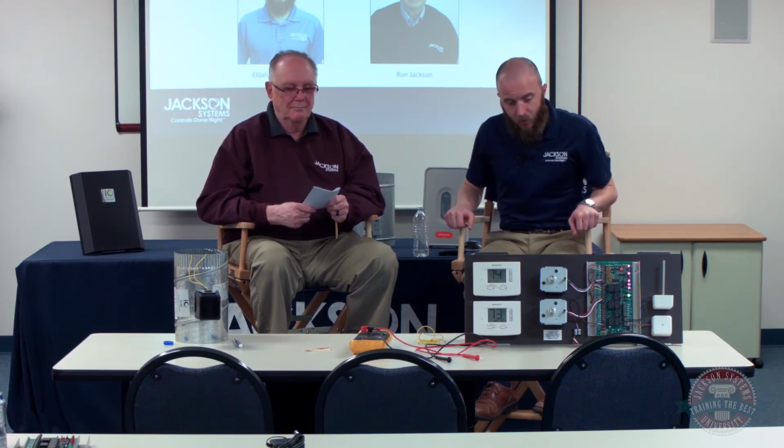However, all of the inverters that I know of use some kind of proprietary thermostats, whether it's communicating or not. They're typically proprietary, whether it's a Daikin or Mitsubishi or whatever. Basically any kind of third-party zoning, like these I/O controls or a Honeywell or something like that, throws that out the window. Can't do it.